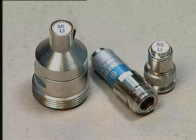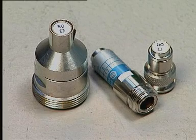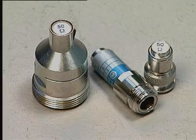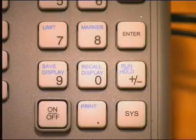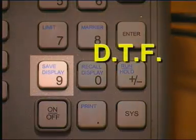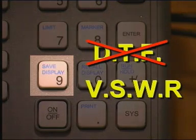The most accurate reading will be obtained when the antenna is disconnected and a 50 ohm calibrated load is substituted. Incidentally, if you need to save the display, then save the VSWR data, not this distance to fault screen. Distance to fault and other data may then be recalculated later.